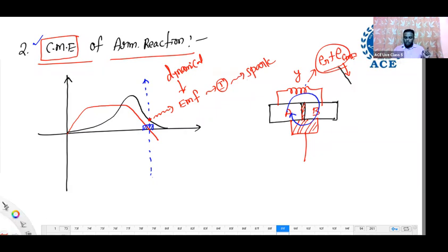Okay. So if you don't reduce these effects, observe what happens. Already due to reactance voltage, there is some voltage. Now additionally, there is the cross magnetizing effect. If the sum of these two voltages exceeds some value, generally, the mica insulation here will withstand approximately 20 to 30 volts, 40 volts, not more than that.